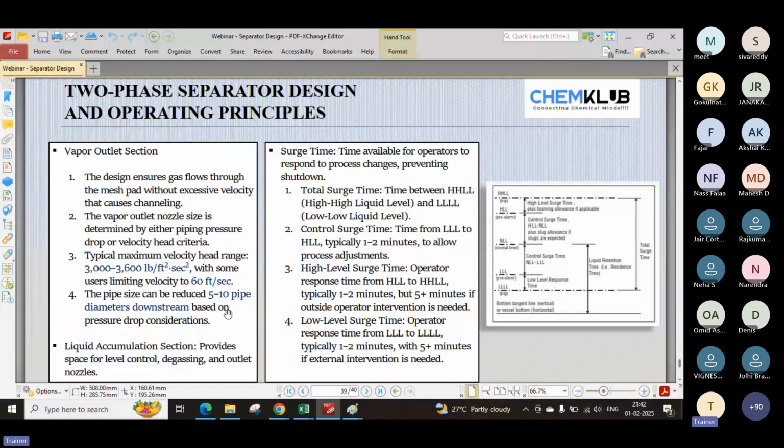That is what we have seen, that is how to control the liquid level, low liquid level, then NLL, and then there is a surge. Suppose the feed is coming from your own platform, or from your own platform but with lift gas or injection gas, or from an adjacent platform. You have different flow multipliers to consider for the incoming feed.